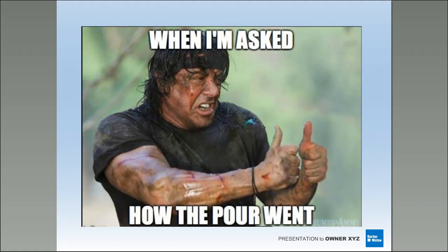Rich, acceptable or not? So fibers in polished concrete, acceptable. We do it all the time. Again, be cautious of what you're doing with it. If you're using a macro fiber, a heavy synthetic, probably stay away from any type of cream polish because it's going to look like you threw hay in the top of that slab. It's not going to be very attractive. So if you're doing a surface polish, I'd probably go with a steel fiber or drop back down to rebar or mesh. All right.